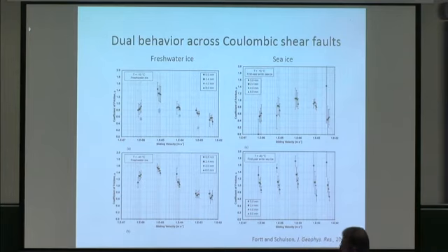Minus 10 is one set of results, minus 40 is another. Don't worry about the difference. And don't worry about the different points here taken at different points on the sliding, whether at 2 millimeters, 3 millimeters, 8 millimeters. The point to note, again, two regimes: a rising branch at the lower speed, a decreasing branch at the higher speed. Both temperatures, both materials. And again, the similarity is much greater than the difference, one material to the other.